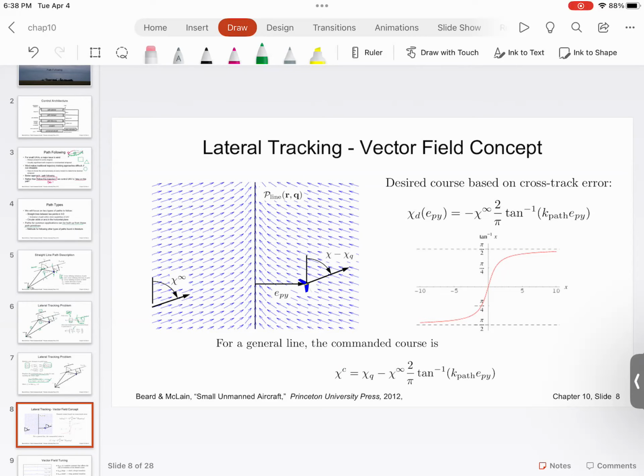Now, there are multiple ways to do the course correction. One crude way of doing the course correction: if your UAV is going in this direction, you basically turn the heading and start going in this direction. But please try to understand, as you cross this, you again change and then you go back. Cross this, go back. Cross this, go back, and kind of oscillate. That was the previous algorithm.